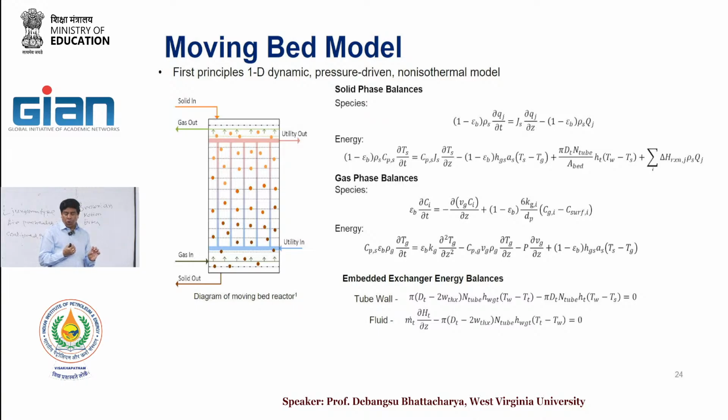Every time you are heating up the solid, in a typical system, that's why in many cases people like pressure swing adsorption, where you decrease the pressure and the compressor takes the load. But here, if you have to heat up the entire amount of the solid, that may require quite a bit of heat.